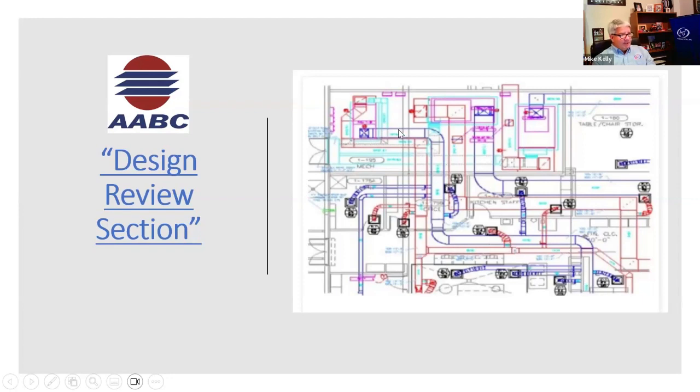The other thing that happens in a design review from a testing and balancing standpoint is duct sizing. We know that this ductwork coming out of the air handling unit, the blue duct, is such a size, and does it increase? Is the aspect ratio correct? Meaning it's not 36 inches wide by 4 inches tall. Is it the correct sizing for velocity, meaning it didn't get squished down to take the velocity well over and create a pressure drop that the system can't handle unexpectedly.